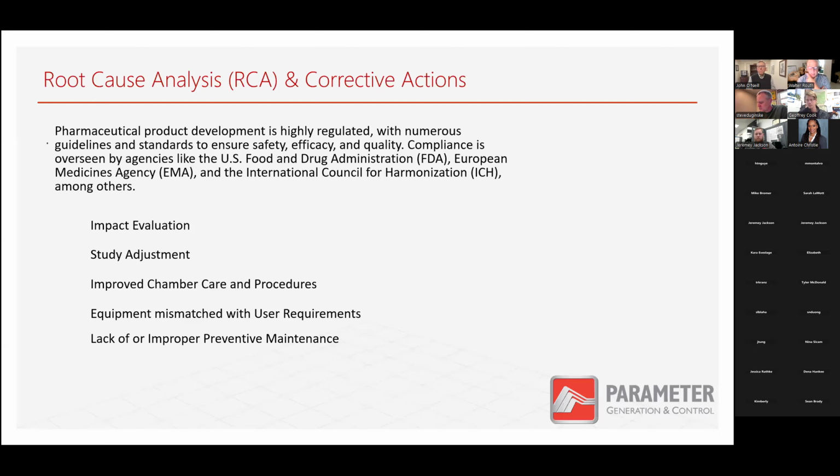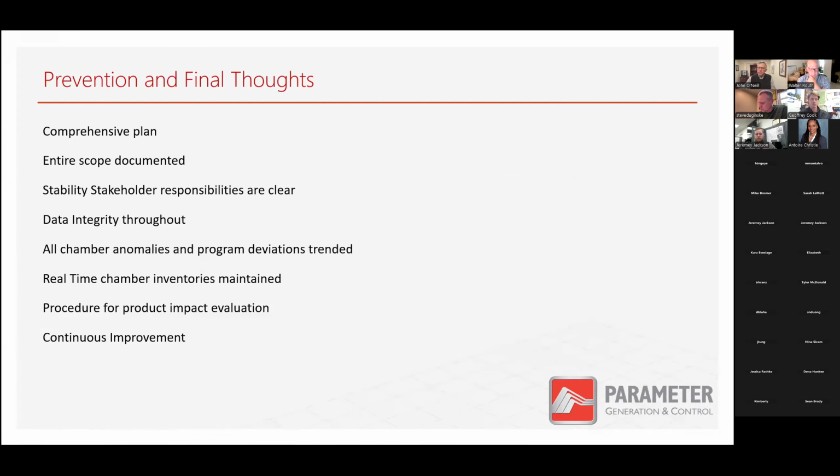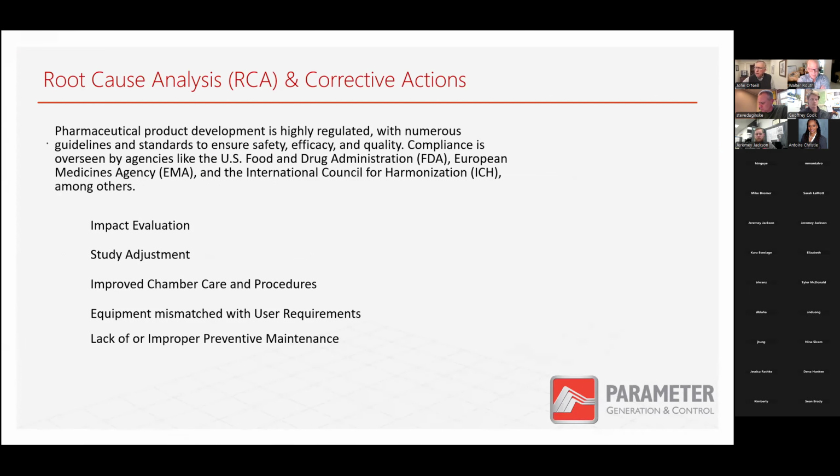Yeah, I completely agree. In a past life for us, we had a graded scale where there were certain amounts of time given for the severity of the excursion. So we were allowed up to 24 hours if it was less than 2 degrees and I believe less than 5% humidity out of range. We also had one where I think we had 2 hours if it was greater than five. And depending on the temperature as well. I mean, if it was minus 80 and it's going 10 degrees out, it may not matter as much. So we built a pretty detailed procedure around that.